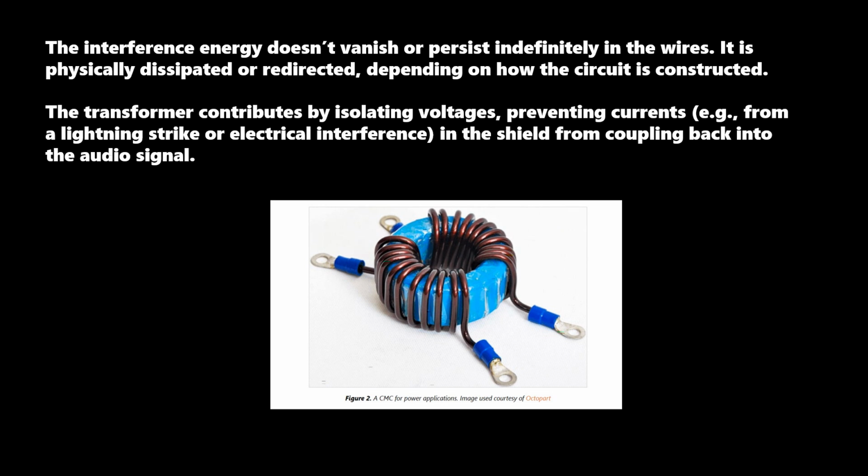I didn't mention in that video enough that in the telegraph, instead of swinging two wires between two telegraph places, you'd have one wire, and then the one wire would go into the ground in each place, and the ground would serve as a wire between them. So earth served as that second wire. And it's the same thing in these balanced audio cables, right? The pin 1 wire, the ground wire, in a sense implies a second wire. You just don't see it because it's using earth as that wire.